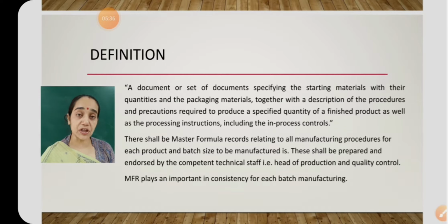Now after granulation, I will be shifting it into the granulator, and from the granulator it will be shifted to the dryer. After drying, it will be sieved again, and after sieving, what is going to happen over here? Now we will again pass it through the sieves, and we are going to add the other ingredients like disintegrating agents, lubricating agents, anti-adherent agents. All these will be added and mixed, and then these components will be utilized to make the tablets by the wet granulation method.